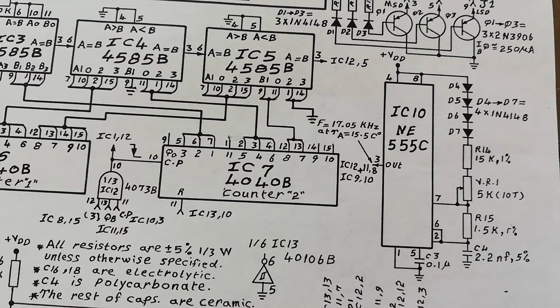I'm not going to discuss how the 555 timer works, but generally, as you all know, you have a charging cycle and a discharging cycle. The charging takes place across these diodes and these resistors in here and this one too, R15. So the charging current will go through all of these, but the discharging current will go only through R15.